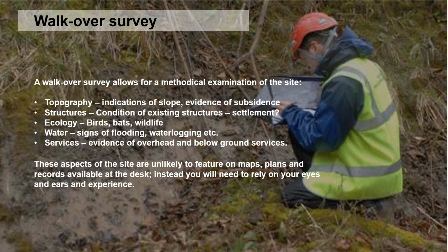So once you've done your desk-based research, you have to go to site. You have to understand it. You have to walk there, use your eyes and ears to consider all the things that you've learned in the desk-based research. A walkover site is essential for doing that. There's only so much you can learn from 2D drawings or historic records.